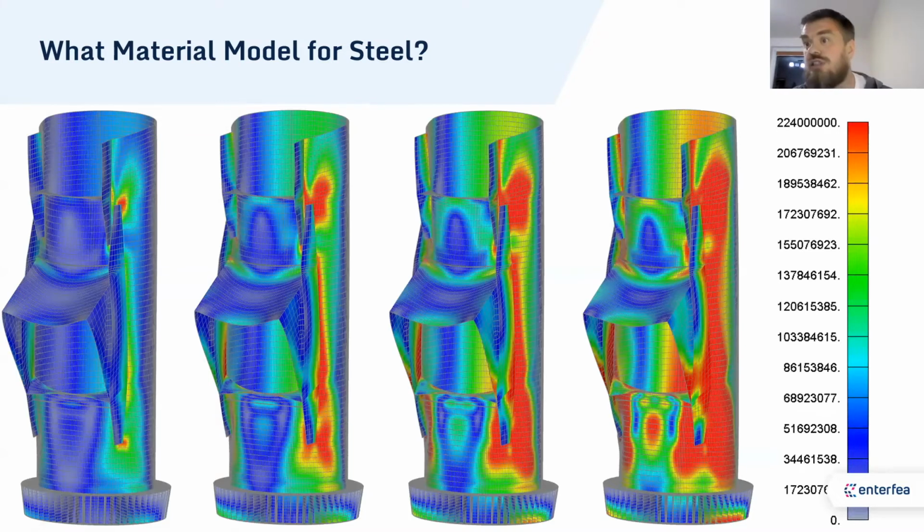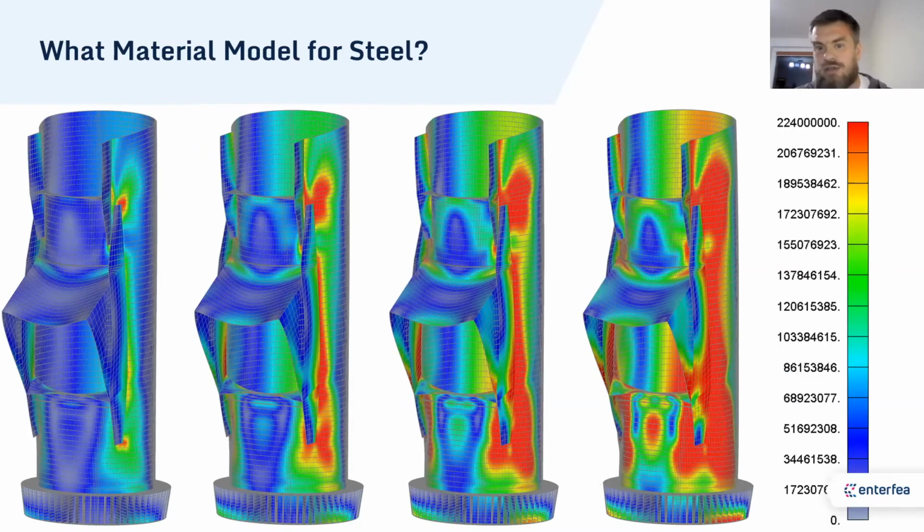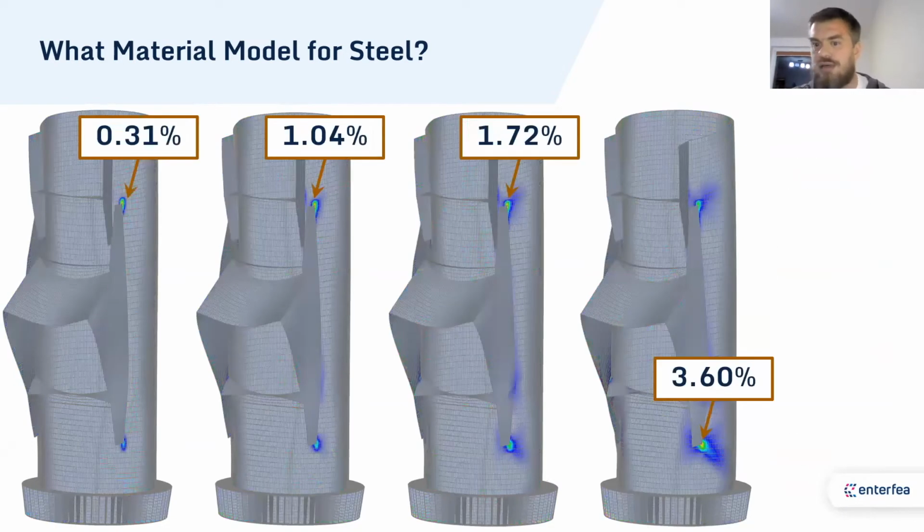And then this is the material model that I'm using, although we still haven't answered the question of whether there is anything else than plastic strains. Because, okay, I cheated. I showed you the stresses. I could also show you plastic strains, and you can say, here plastic strain is 0.3, 1.4, 0.04, 17, 36. You can say, I'm willing to accept this much plastic strain. This is failure. So firstly, you see a clear criterion that was not present. It's not the stresses that would dictate the outcome, but the strains.